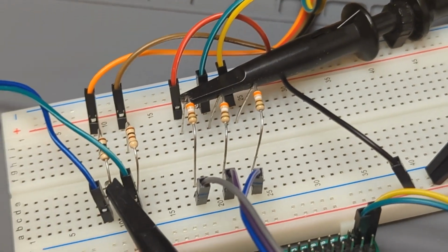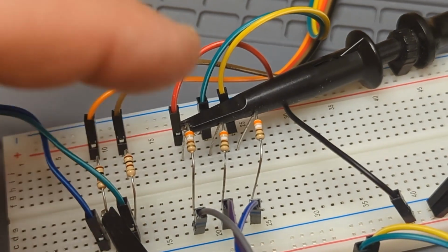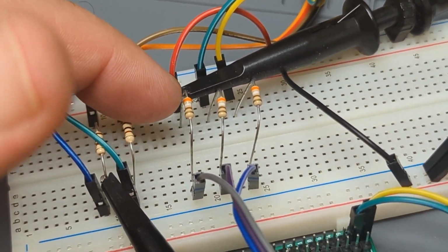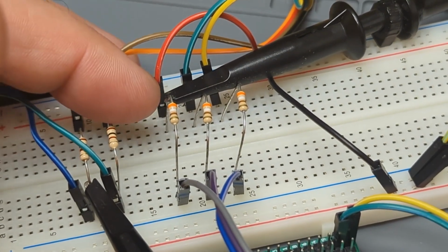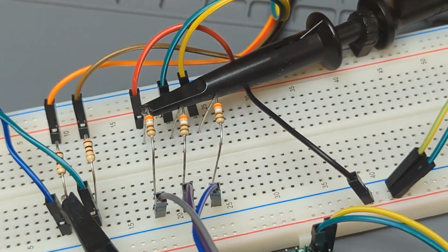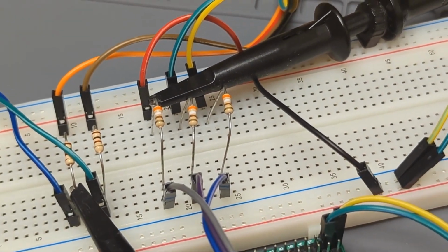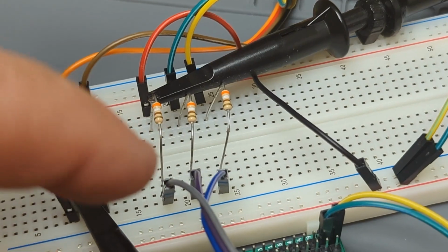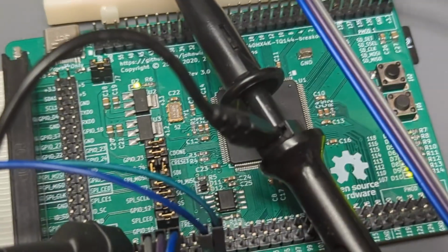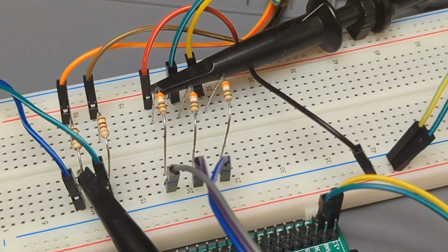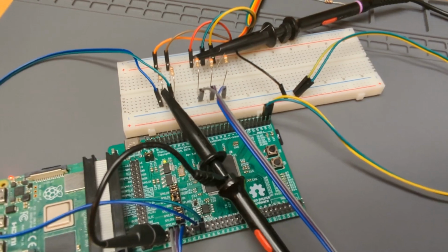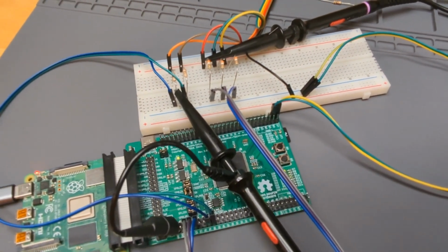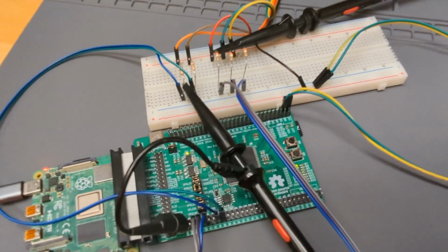So this turns out to be a pretty good size to get the right voltage, which is supposed to not exceed 0.7 volts, by the way. The analog for the R, G, and B value should never go over 0.7. That's the maximum brightness signal that's supposed to come out of this wire, which would work fine at around, like I said, 330 ohms in series for this design. If we had an FPGA, or maybe you put an LVC245 bus driver chip in there to buffer the signal to get the current up, you could put a smaller resistor in there. But don't go under 330, okay? So that gives us our white screen.